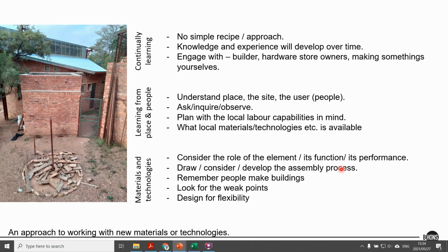Because you start at the very bottom and then you bring it up, and as you're drawing up, you realize, oh, wait a minute, there's a new problem, and so forth. So find ways that you can think through the assembly process. He then said something very important, we spoke about it a few times. Remember that people make buildings. So how can you fit someone into that space? How can a large person get into that service shaft to fix the pipe in the end? How can you get to that end of the roof? Or how do you get to this flat roof section here, to fix it in the end?